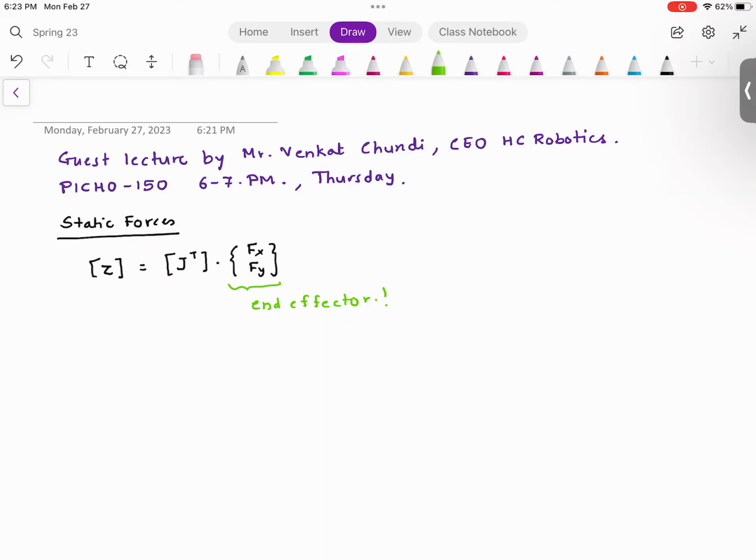The second thing is, imagine you have an end effector. You want to make sure that the robot configuration does not change under the self weight of the end effector. So this equation that I have shown you on the board is important to understand the holding torque and what should be the maximum torque capacity of the servos so that the robot operation is smooth.